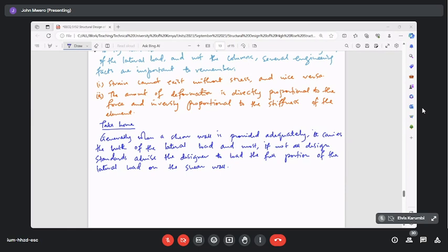And then you take your calculated lateral load and put it onto the shear walls of the building, 100%. So you would analyze the shear wall for 100% of the loads, and I'll show you shortly how you would do that if you are doing this calculation manually.